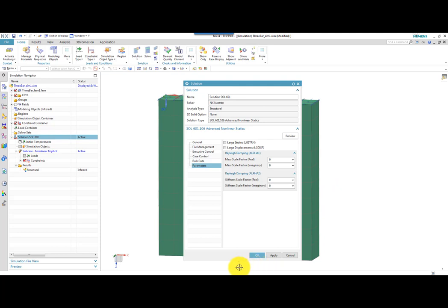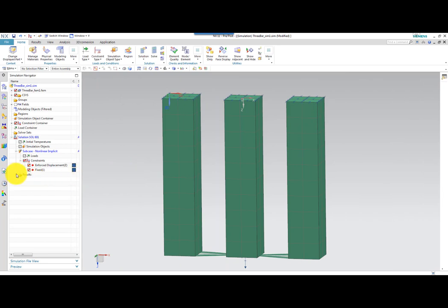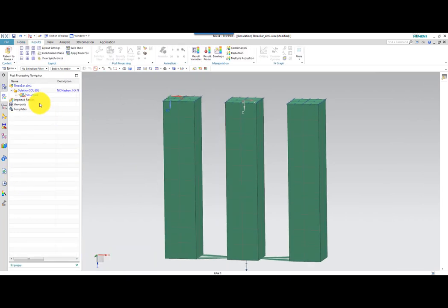When my applied displacement is small, that means 0.12 millimeters, like I do in this case, I don't want to initiate or apply large strains and displacements in the simulation. And that's partly because in the NAFEMS book, they assumed a linear relationship between displacements and strains. And also I used engineering stresses and strains in my inputs. So I keep them like this, not activated. And then we are ready to run. It takes a few minutes on my computer, and then we can open the results.